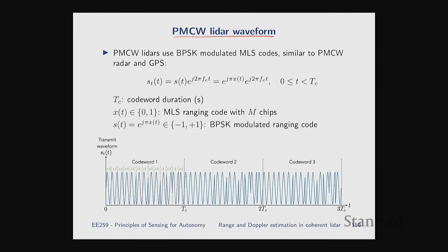Now, before we talk about this, we are not going to go into a lot of depth here because PMCW LiDAR, to my knowledge, has not been commercially deployed yet. Although it's a very interesting technology, and there's a lot of very interesting research being done on it. For some technological reasons, mainly because it requires ADCs with very high sampling rate, and the DSP gets a little more complicated, it has not been commercially deployed.